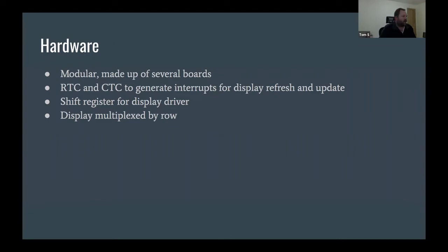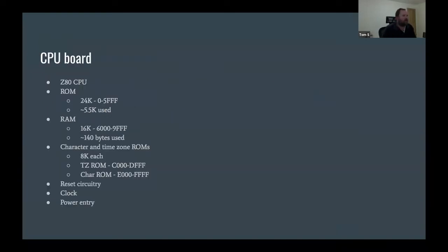And the display is multiplexed on a row by row basis. So the shift register is basically big enough to hold all the bits to drive every single segment on one row of the display. And we'll go into a few more details about that.